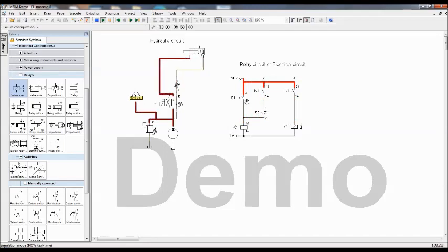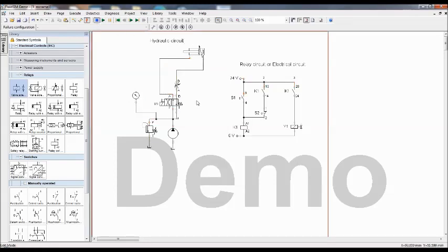Storage means once S1 is operated, you don't have to operate the switch S1 continuously. Once it is operated, that is enough. And then by operating switch S2 only, it is going to retract. So S1 is a set instruction, so the data will be continuously stored in the K1 relay, and when S2 is on, it is erasing the S1 data. S1 is like an on signal, so that data can be stored and can be erased using S2. So this is the working. And in the last video I've shown how to submit the assignment, so again, you can copy these circuits to the Word file, and you can submit it.